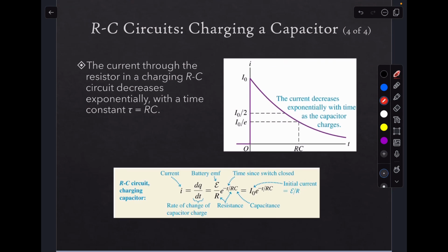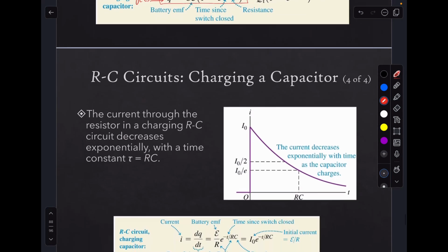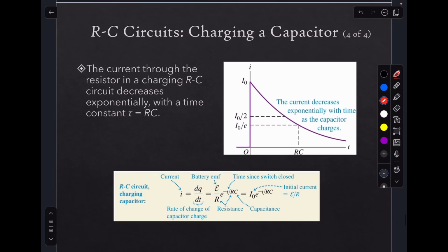So we looked at the charge. So what happens to the current in that circuit as a function of time? While the capacitor is charging, there's a finite current running through this circuit. So every charge that gets donated out of that current to the capacitor reduces the current a little bit. So the current should decrease exponentially as we charge a capacitor because it's constantly donating charge to the capacitor. And eventually that current should reach back down to zero.